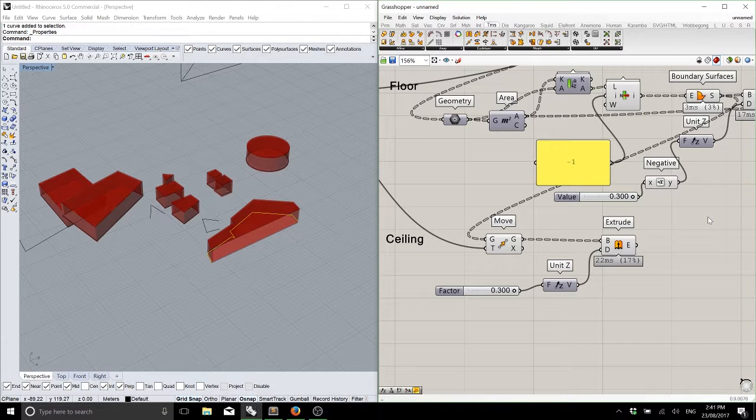Rhino isn't very good at doing the sections that Revit is capable of doing, but that's a section making tool. It's not BIM. BIM is the knowledge that sits behind all of that in the objects, so that when you cut a section, it knows how to treat that object in that section. So glass comes out looking like glass and timber comes out looking like timber.